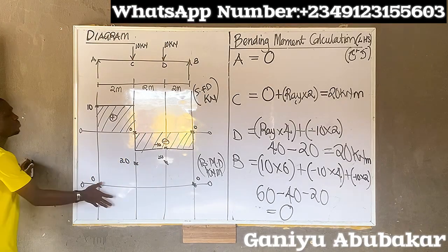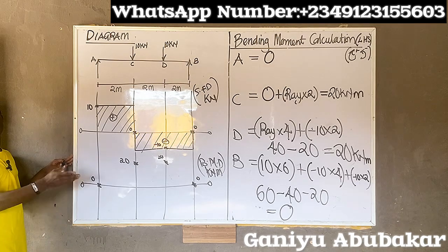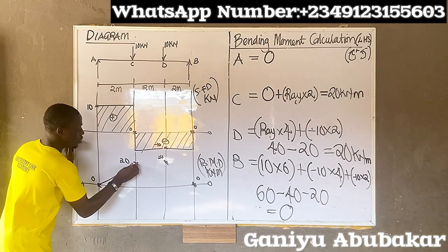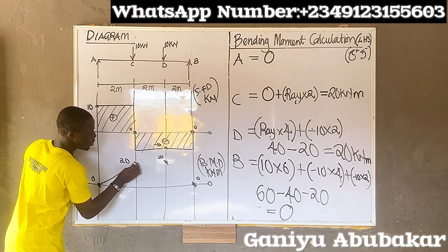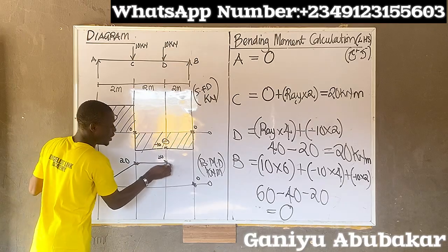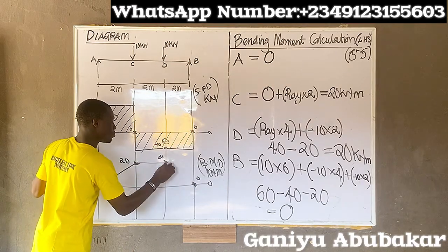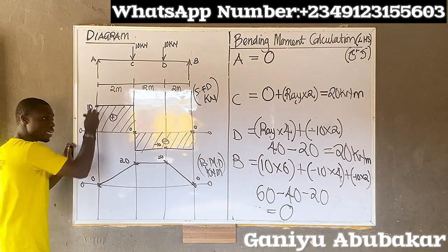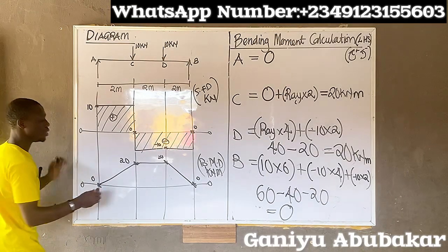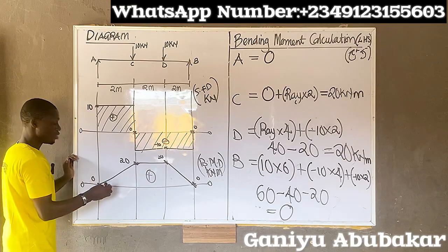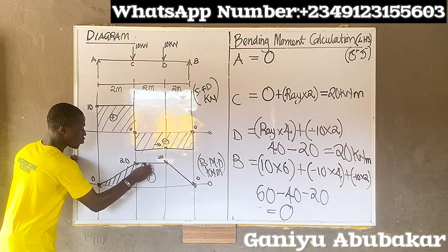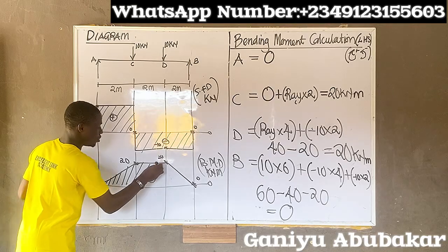When it comes to the inclined line, this one goes this way. Just try to make it inclined. This one I cannot incline because it is straight, level. Then incline down this way. It's a straight line, not a curved parabolic one. All right, so this is my bending moment. This is a positive region. Just shade it.